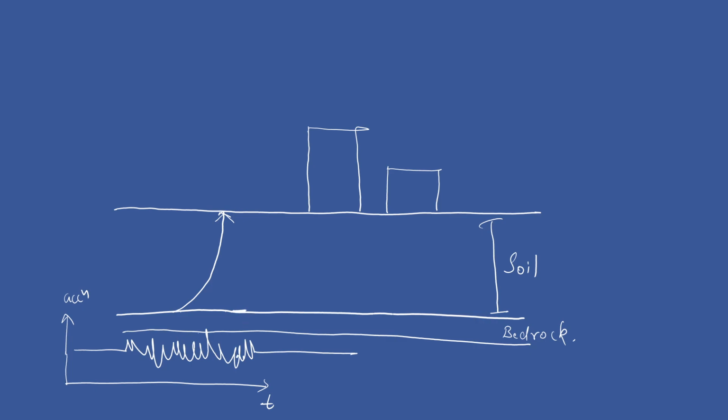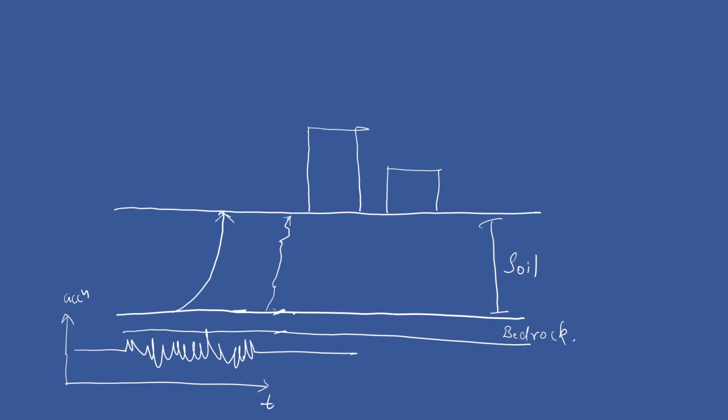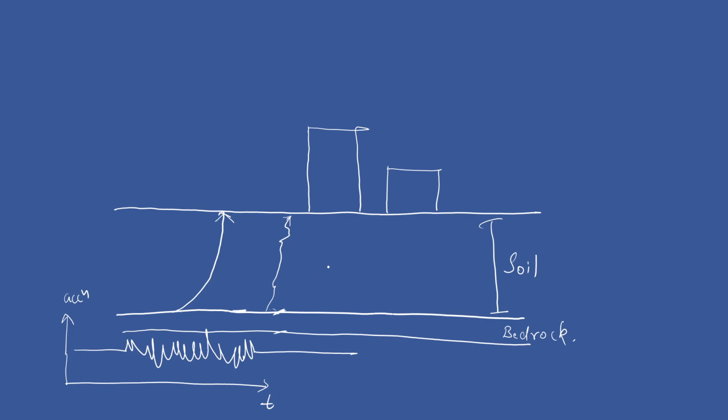Okay, so therefore whatever acceleration forces or seismic forces are available at this particular point, those same seismic forces will be available at this surface also, and those seismic waves will travel through the soil. So whatever seismic intensity is available at the base of the soil, that same intensity won't be available at the surface of the ground, because in the soil you'll be having some damping properties.